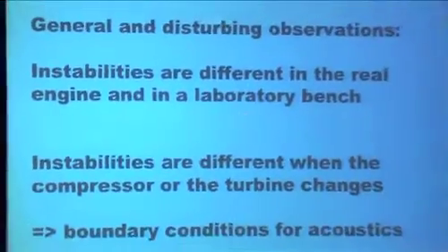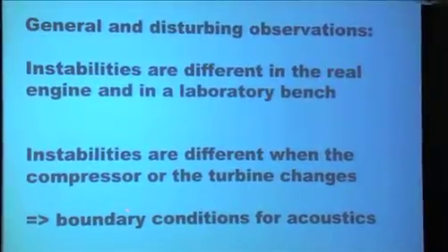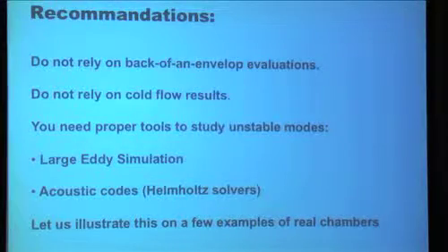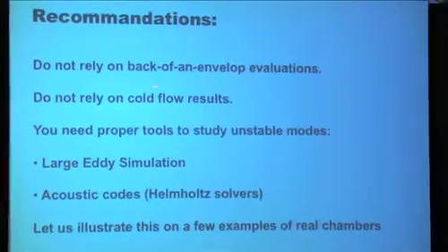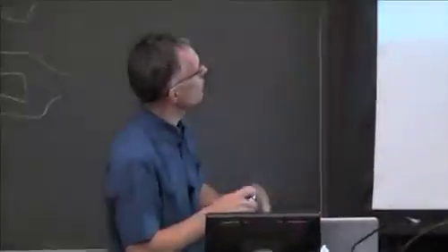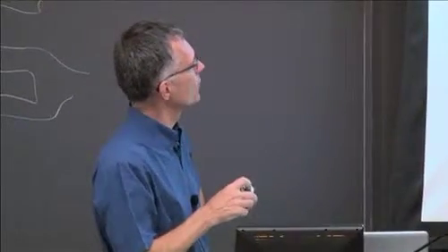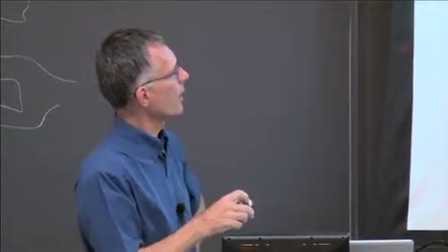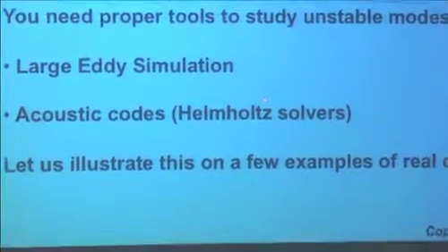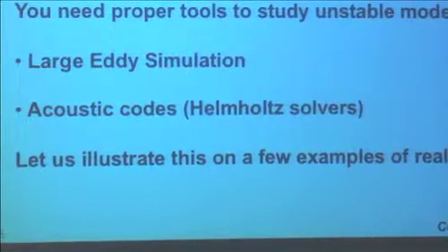As I said before, what you see on the real engine and what you see on the laboratory bench will be the same only if you have the same impedances. If you don't have the same impedances, you cannot compare. So if you want to work on thermoacoustics, do not write frequencies equal that, so it's the cause of the problem. It's not true. You need basically to use these two tools I have presented: large eddy simulation codes to do the full computation and to do the self-excited modes, also to do the FTF if needed, and acoustic codes to look really at all the modes in the system.